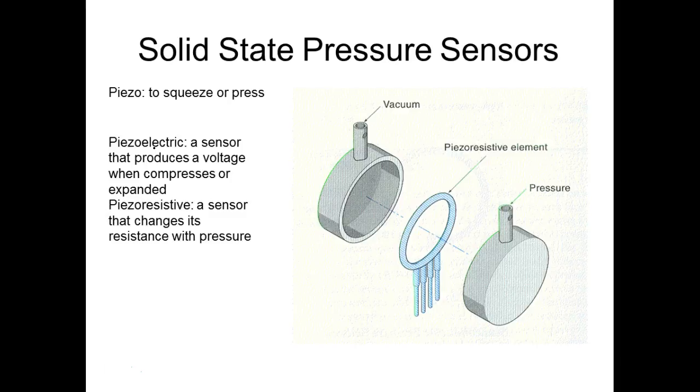The problem is piezoelectric only generates it. If it was truly a pressure sensor, it would generate that voltage all the time. But it only generates that voltage when you strike it with a force, right? You understand that? So piezoelectric pressure sensors only look at what? When the pressure does what? Changes. So the pressure changes. So it's real good to look for pressure changes.